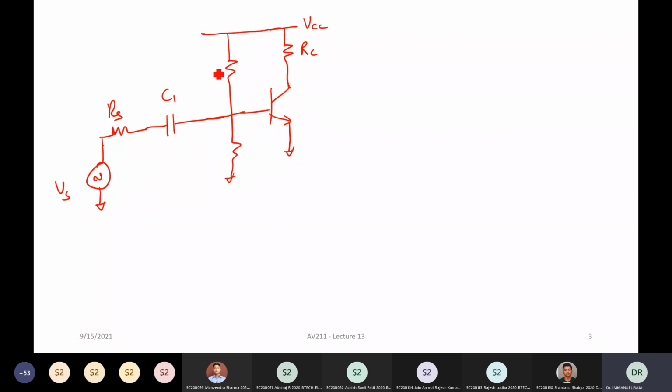If you don't have this, you can have a DC current path like this. And the DC current sometimes can damage your sensor also. Even if it does not damage your sensor, you are unnecessarily wasting current by pumping it into a sensor which does not need it. Also, it may even happen that the sensor by itself might need some different DC point.